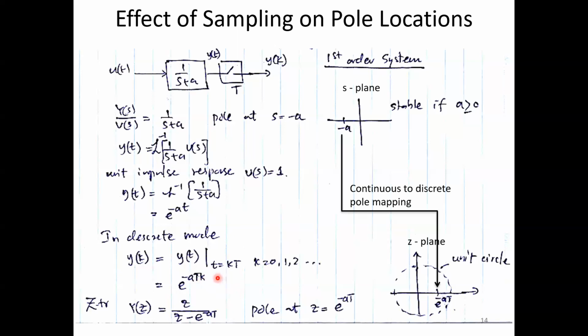So that is one thing, and we know pretty well how to read this expression. If you look at the Z transform table, if you have anything to the power k, the Z transform is z over z minus that thing, to the power without k. You put it over here. This is the time domain, and this is the Z transform. You can see the time domain e to the minus aT to the k. You take this k out and put the rest into this format, and that is the Z transform of that discrete time signal.